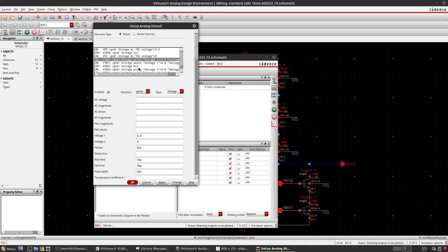V30, we should be giving pulse 0.8 and period is 160 nano, rise time 50 pico, fall time 50 pico, pulse width will be 80 nano.